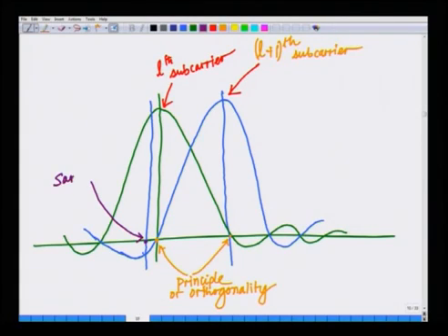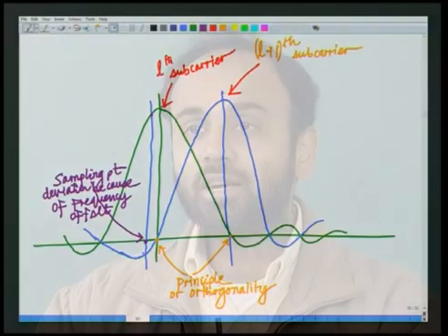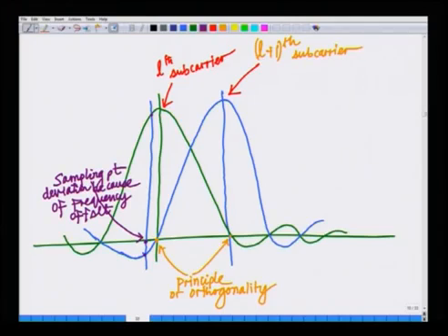This is the sampling point deviation because of the frequency offset, and as you can see, when I sample here, the value of the desired subcarrier is lower, and more importantly there is interference from the adjacent subcarrier.